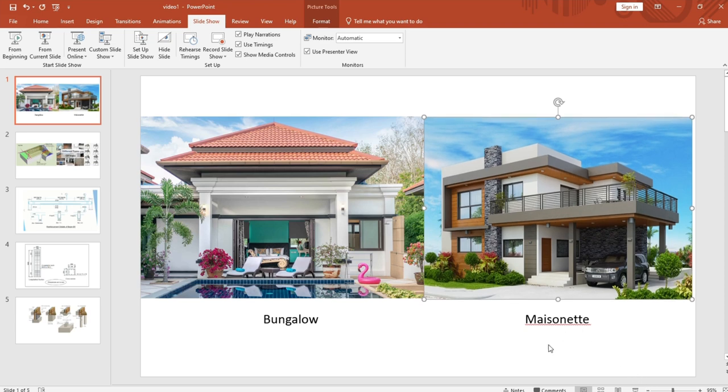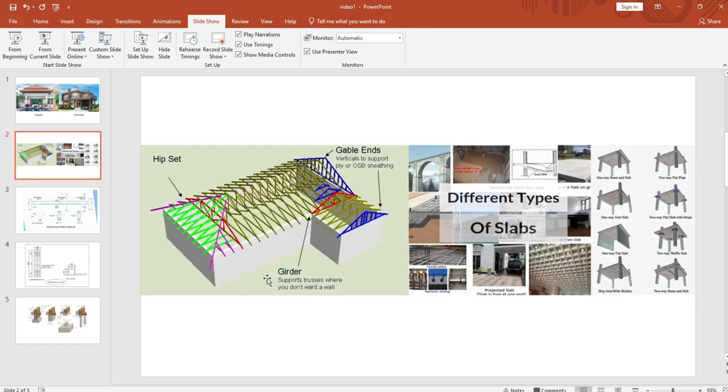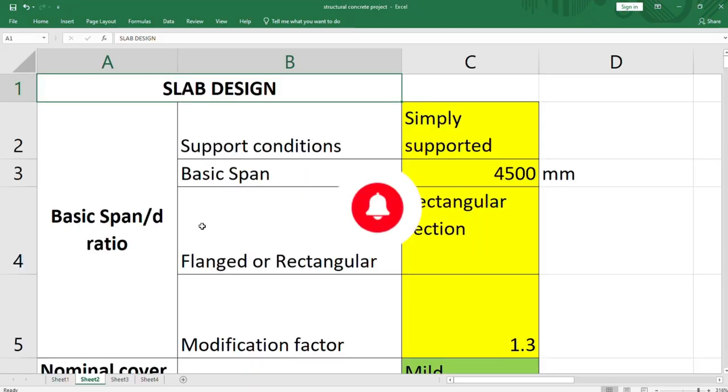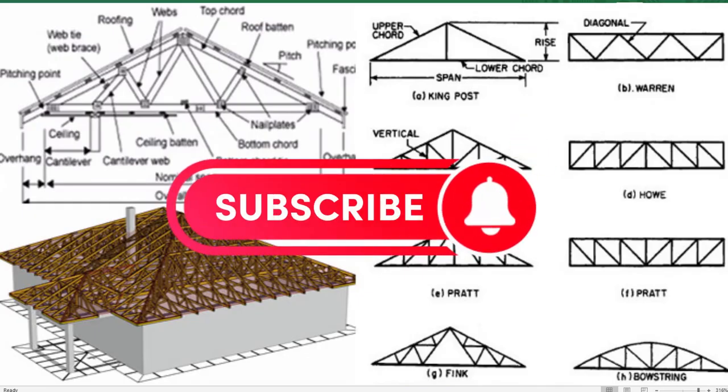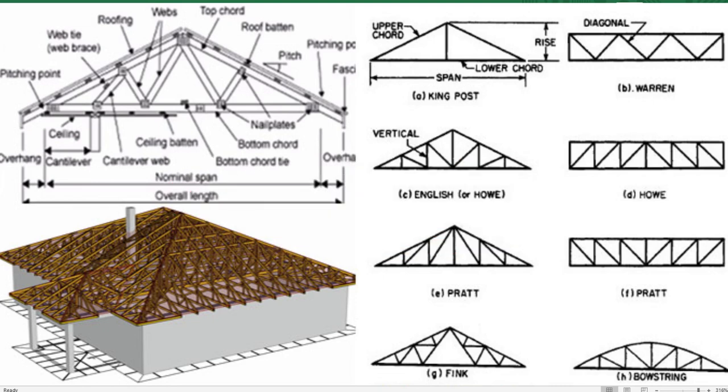And when you are doing all this, you have to design from the top. For a bungalow, you have to design the trusses first so that they can hold the iron sheets. They have to be strong enough. From there you have to check the load that will be borne by that truss, that is the iron sheets, that is dead load. Then the live load, that is maybe the solar system or any other thing that you want to put on the roof.